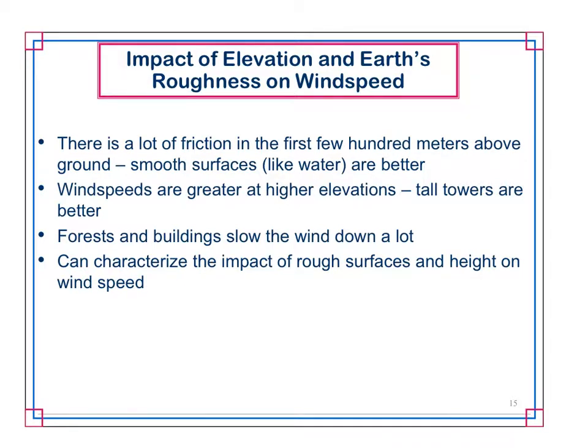You're going to get a different reading at 50 meters from Bangor than you will in the middle of a field. What I mean by that is the higher you go in elevation away from the city in Bangor, the faster the wind speed should be as compared to being out in the middle of a field, because the surface around that field tends to be slipperier to wind than it does to Bangor. And so we talk about that as being how rough is the area around a particular site or a proposed site to wind.